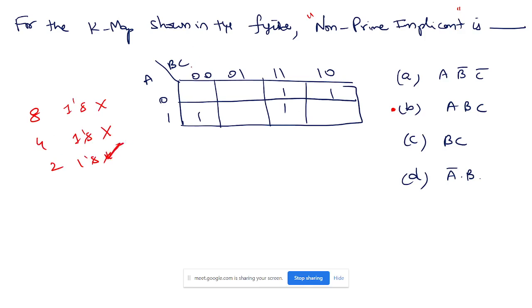First of all, check the gray code 00, 01, 11, 10, right? Correct. So this is one pair. This is another pair. Correct. This is one more pair. One more, not a pair, just a single one. Correct. So we have identified this, right?